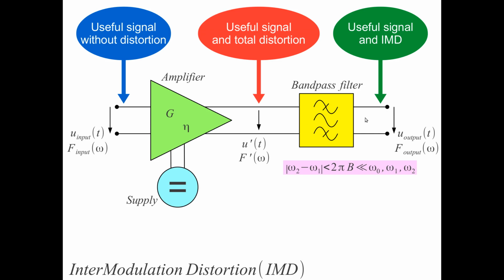And this is just to explain what intermodulation distortion is, and this intermodulation distortion always makes it through the bandpass filter. It is going to corrupt the useful signal for our receiver, but it also generates some signals outside our useful bandwidth, the bandwidth used by other users, causing crosstalk to other transmissions, over radio or over optical fiber. This always happens, and this cannot be removed. So this is the problem here.